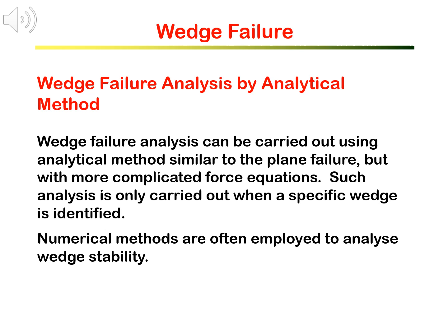Such analysis is only carried out when a specific wedge is identified. With the development of discontinuous numerical methods, block element numerical modeling can be employed to analyze block and wedge stability.